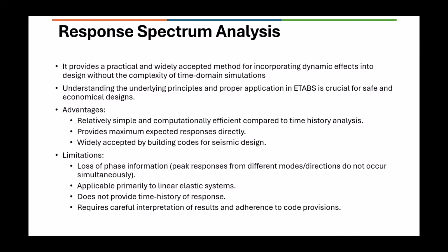And it is applicable primarily to linear elastic systems. That is also fine because most structures are linear elastic unless we introduce nonlinear devices such as isolators and dampers. Even then, it provides a very good start for an analysis to get some numbers, and response spectrum analysis is going to help.